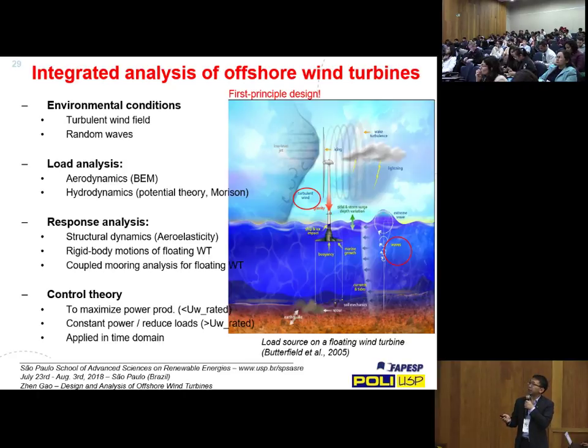And also I mentioned that the blades are relatively long, so there's an issue about aeroelasticity, so that the blades deform dynamically due to wind turbine loads on the blades, and then you have to evaluate the loads at the deformed position of the blades. Similarly, we may also consider hydroelasticity, but in many cases, the floater is considered as a relatively rigid structure. So basically, you look at the rigid body motion of the platform.